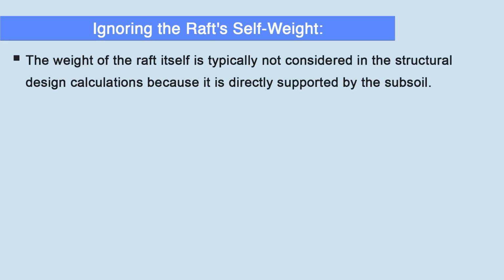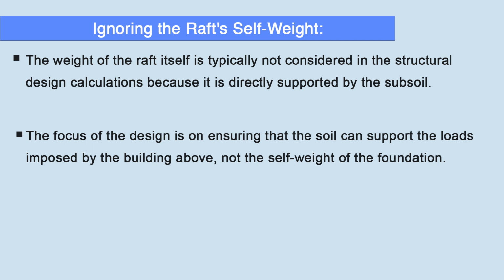Then the next is ignoring the raft's self weight. The weight of the raft itself is typically not considered in the structural design calculations because it is directly supported by the subsoil. The focus of the design is on ensuring that the soil can support the loads imposed by the building above, not the self weight of the foundation.